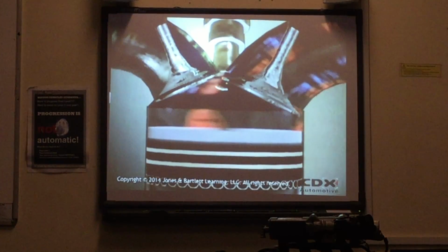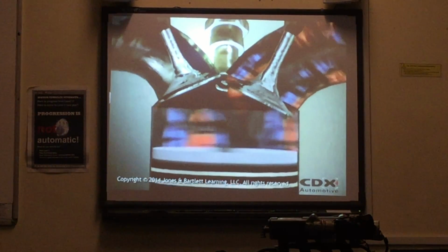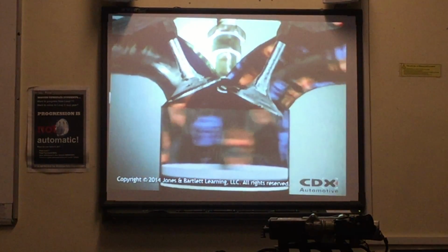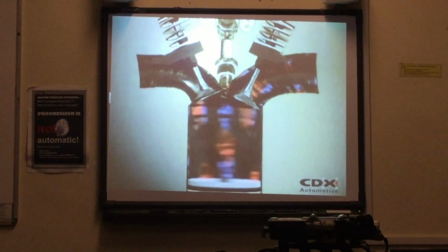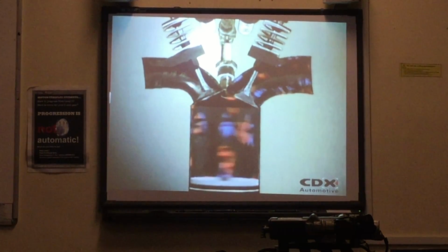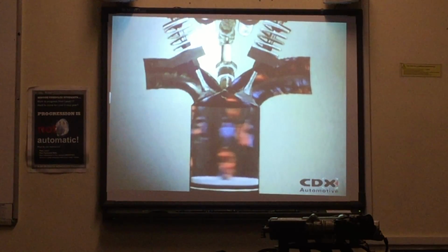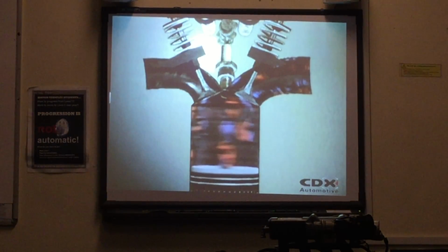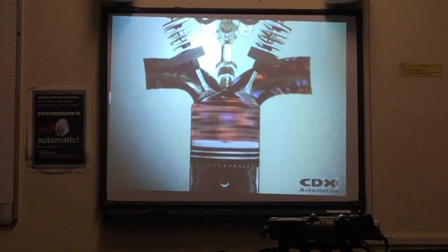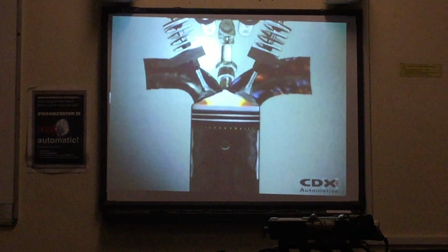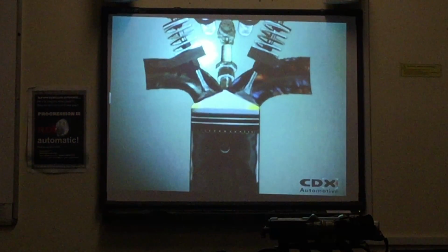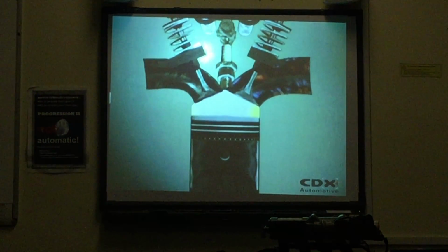This is a cylinder for a 4-stroke petrol or gasoline engine. The first step is to get the air-fuel mixture into the chamber. The mixture enters through an inlet port that is opened and closed by an inlet valve. This is called intake. Next is compression. The piston compresses the air-fuel mixture into a smaller volume. A spark across the electrodes of a spark plug ignites it, and it burns. This burning is called combustion.